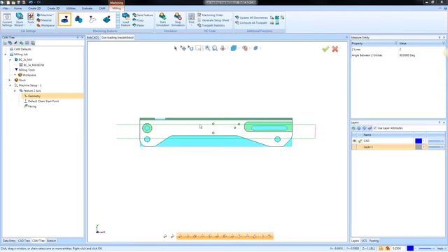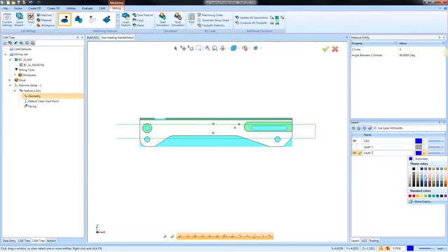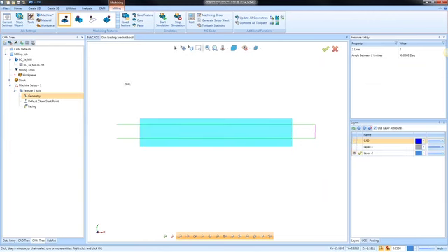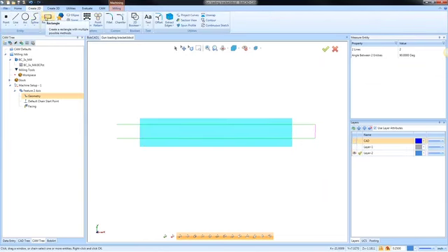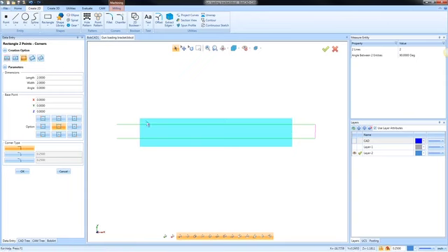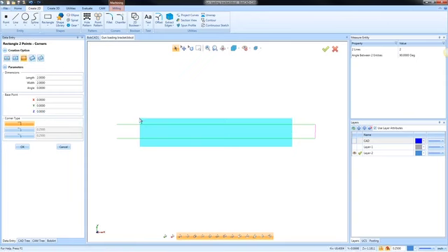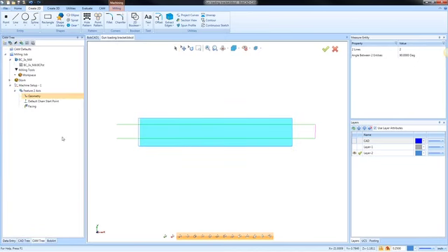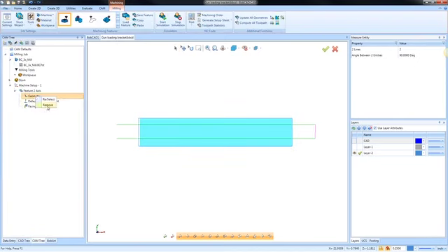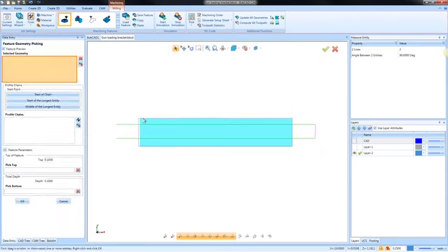If you wanted to create a different boundary instead of that face, what you could do is, let me go to a different color here. What I could do here is just sketch a rectangle. You could come up and say, a 2-point rectangle, and we'll say starting from here and going to there. All right, so that gives me a boundary. Instead of selecting that face, we could just use this rectangle.